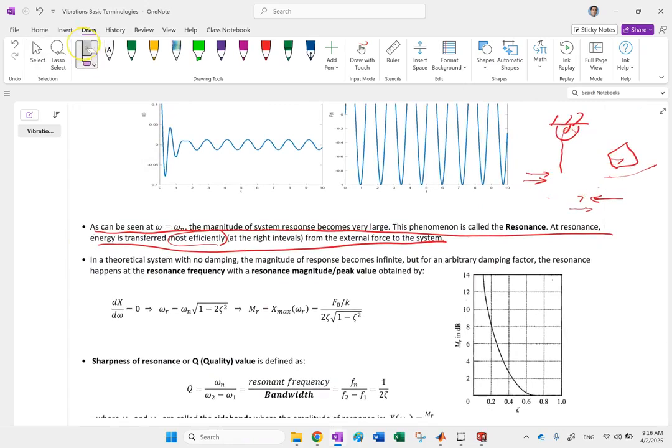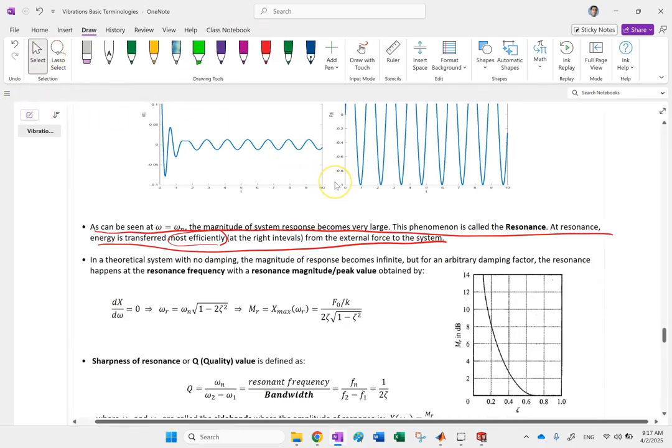And it can have devastating effects in lots of mechanical or structural systems. Like when a shaft is spinning, it has natural frequencies, and you want to make sure that if the load that comes from the gears on the shaft is harmonic, then the frequency of that load is definitely way above the natural frequencies of the shaft, so you don't get a resonance in the shaft response.